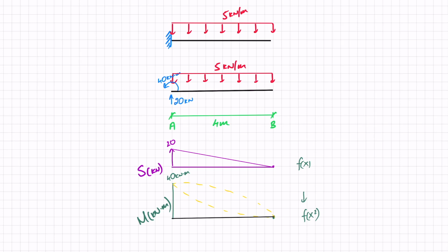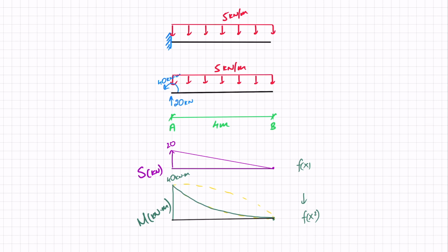The easiest way to go from that, if I'm not looking at maths, is that whenever I have a UDL, the UDL is like the wind, and my beam is like the sail. So if I just use that analogy, I know that this is how my bending moment is going to look. And that's it. Solved.